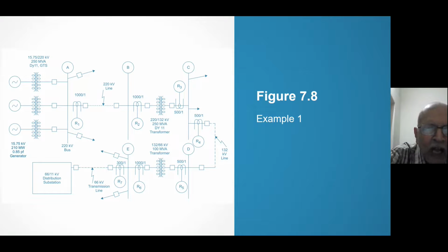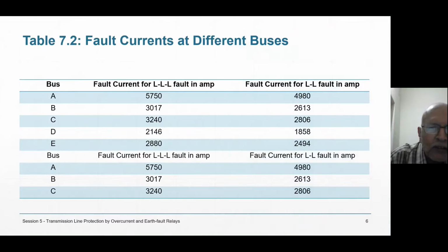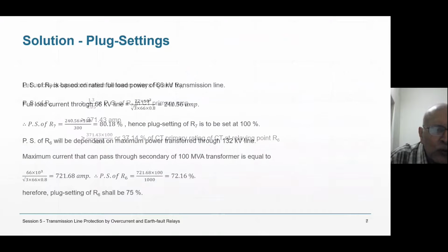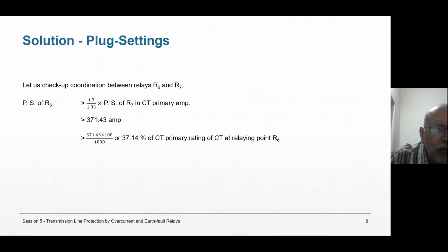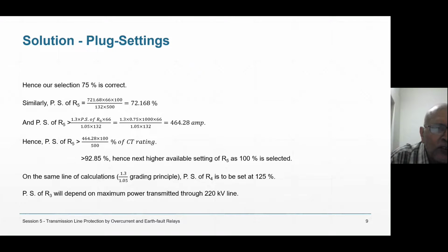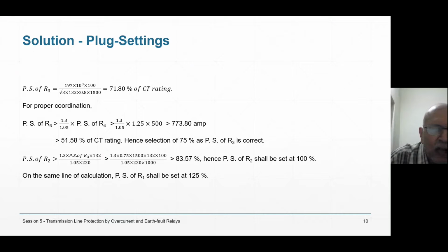I'm checking for R1, right? So what is the plug setting of R2? Let me check out the plug setting of R2. I have yet to check it, I have not done it. The plug setting of R2 shall be set at 100%.